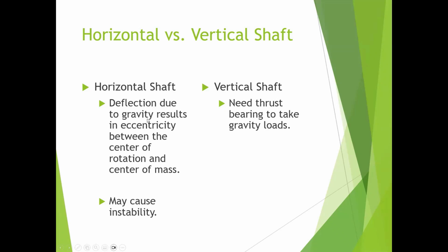Usually the shaft is made of material, usually metallic material. So this has its own self gravity, right? You guys agree? Even theoretically, even if you do not do anything, you have a shaft. This is the left support and right support. So because of gravity, this will deflect to some degree. And no matter how strong this material is, it will deflect.